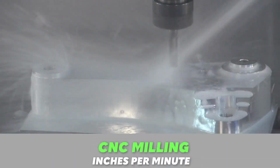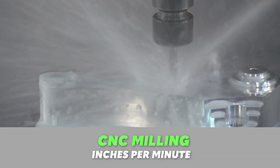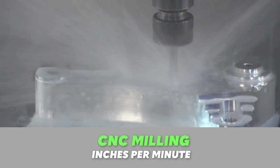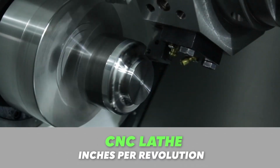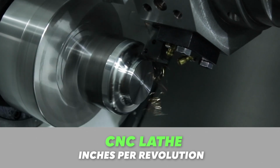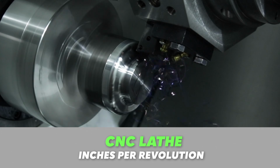You might have noticed that we're defining our feed rate differently than we do on a CNC milling machine. When milling, we typically specify the feed rate, or the speed the axis is moving, in inches per minute. On a CNC lathe, we typically specify feed rate as inches per revolution when turning. There's a good reason we use inches per revolution on the lathe.